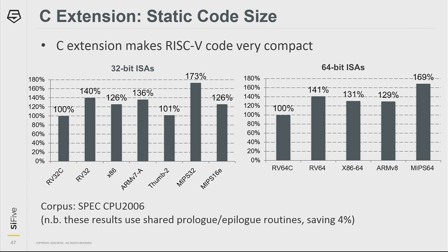It's a very dense ISA. But for whatever reason, ARM dumped it, well, I know what the reason is. They don't care for the implementation complexity in big superscalar processors of providing variable length instructions. But they dumped that in ARMv8, and so ARMv8 is now not a very dense ISA compared to RV64C. And you can see this by the fact that now they're using much larger instruction caches in their IP offerings than they were back when they were doing ARMv7.